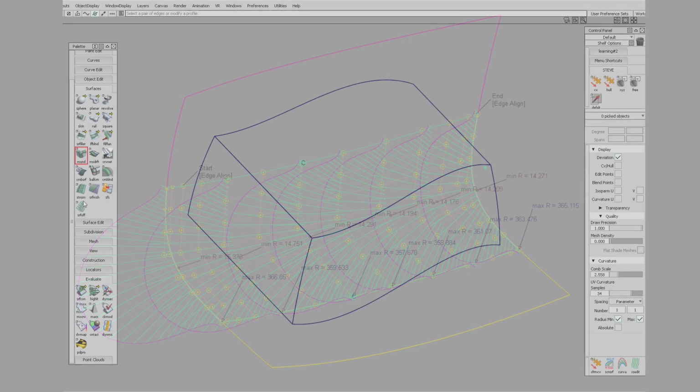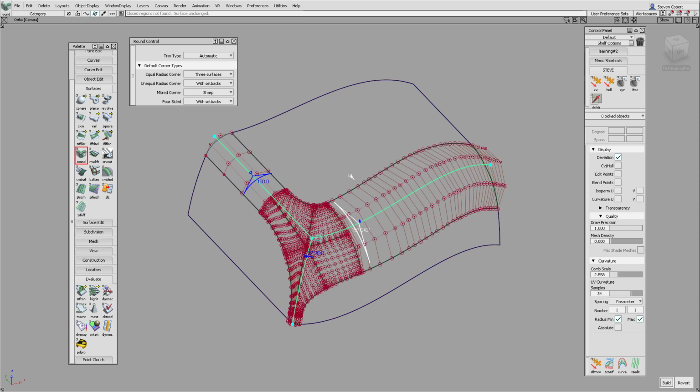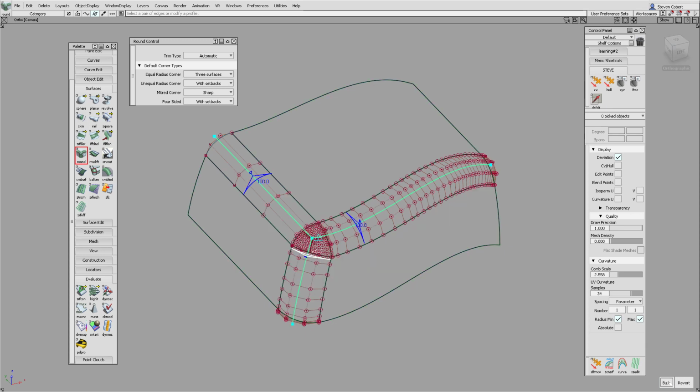The simplest type of fillet is one where the section is circular. The round function can be used to create circular fillets. It is powerful because we can specify different radii on each edge, and the corners are created automatically. But it should never be used for A-class work. Firstly, circular section fillets are rarely used on A-class models, and secondly, the fillets that round creates are poor quality. They're okay for CAS or visualization, but not good for A-class.